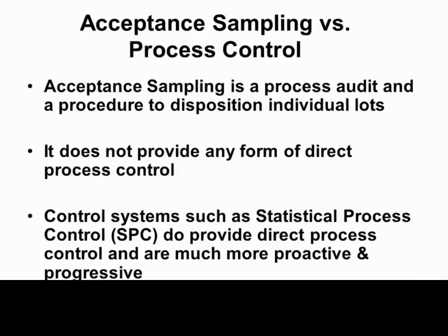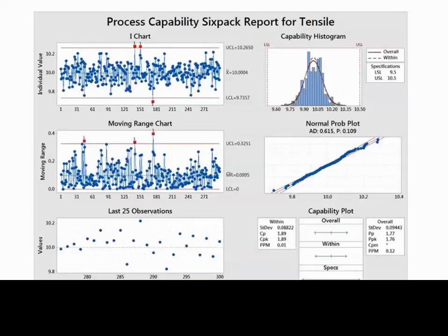It's not a direct stringent process control technique like SPC would be. I'm very much a proponent of trying to do less inspection and more process control by figuring out what in the process upstream needs to remain stable and within what ranges, and using some SPC techniques to ensure that we're monitoring that and reacting more quickly.